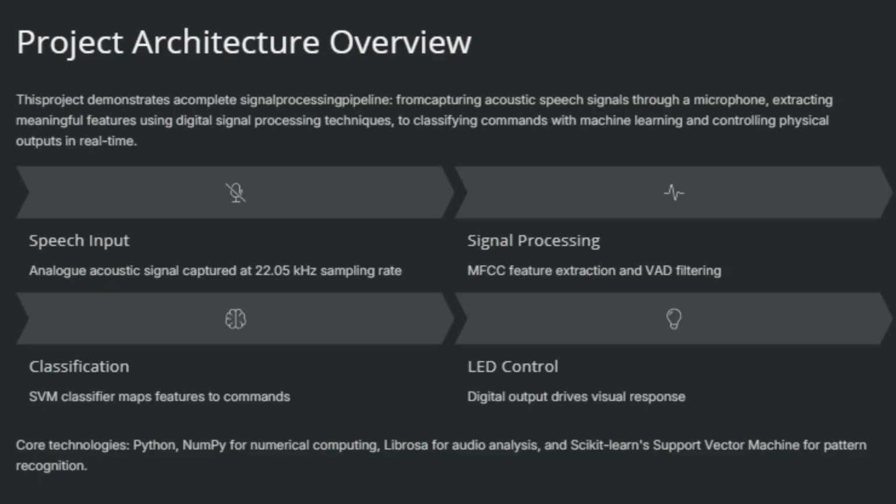This stage is crucial as it ensures that only meaningful parts of the signal are analyzed later. In SNS terms, this pre-processing stage acts as the front end filter network, eliminating unwanted low energy signals and improving the signal to noise ratio before further analysis.